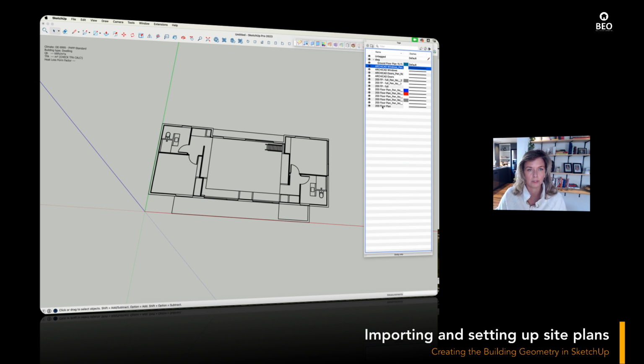So what you can do here is highlight all the names and the tags that you don't really need, and you go to delete and just assign these into the untagged folder. This way you're not deleting any elements from the drawing, but you're keeping your tag folders tidy. And now you're basically repeating the process with all the other components.